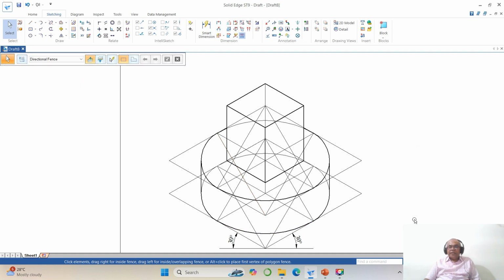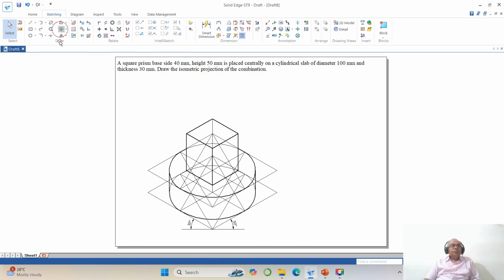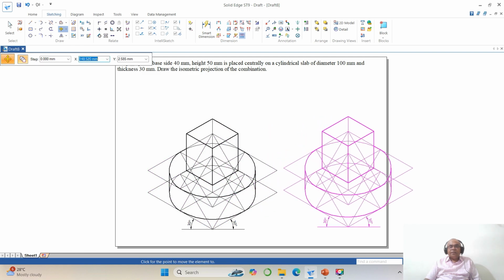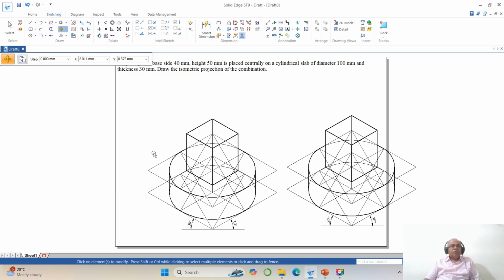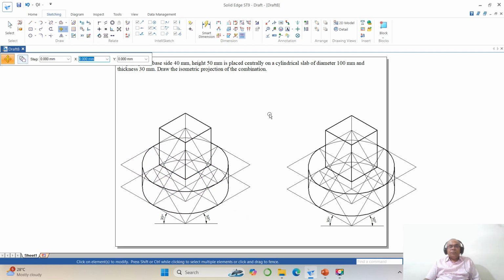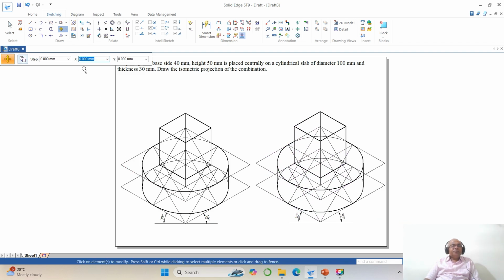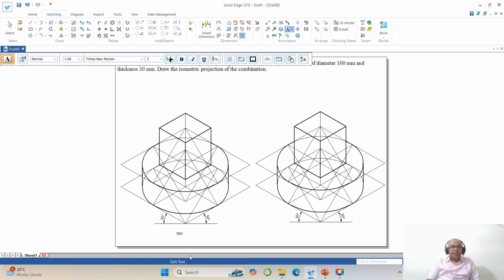You got this. Now again go to fit, again go to move, enable copy, select this entire thing, copy to the next position. Okay, now you go to disable copy, select this entire drawing, move it here. Now you select this drawing, and move it inside. Okay. This is isoscale used. Take the font as 3, enter, and here you type isoscale used. Here also you type isoscale used.